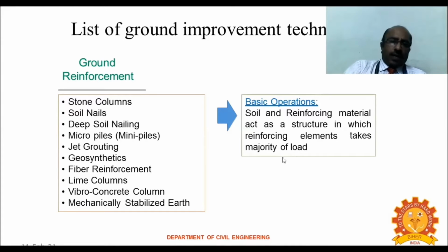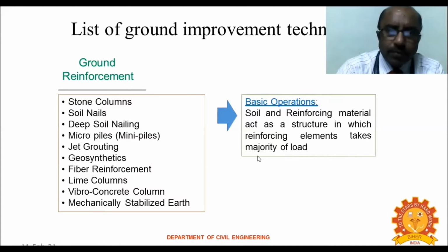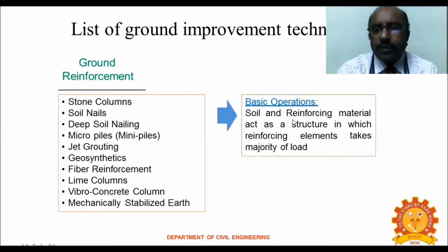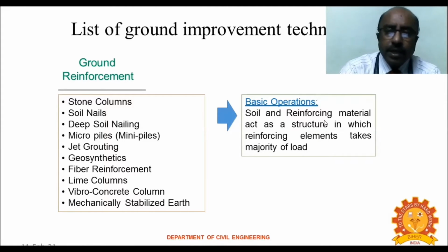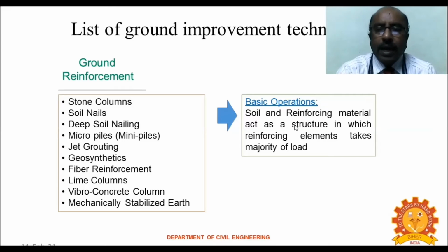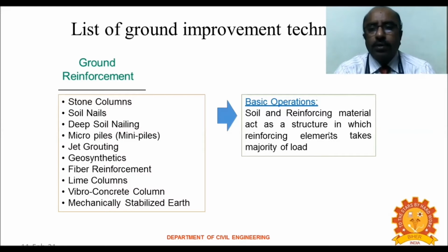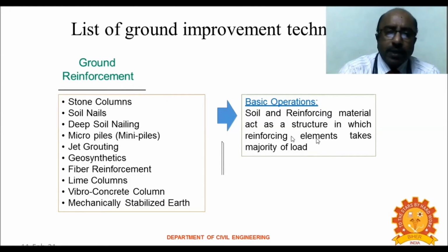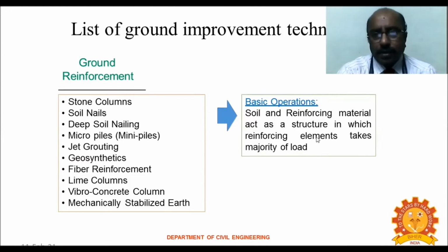And if you go for ground reinforcement, the basic operation involved is that we are introducing a reinforcing material into the soil, and that reinforcing material is going to take up the load. So the major load is taken by the reinforcing element, and the surrounding soil is supporting that. So these are ground reinforcement techniques.